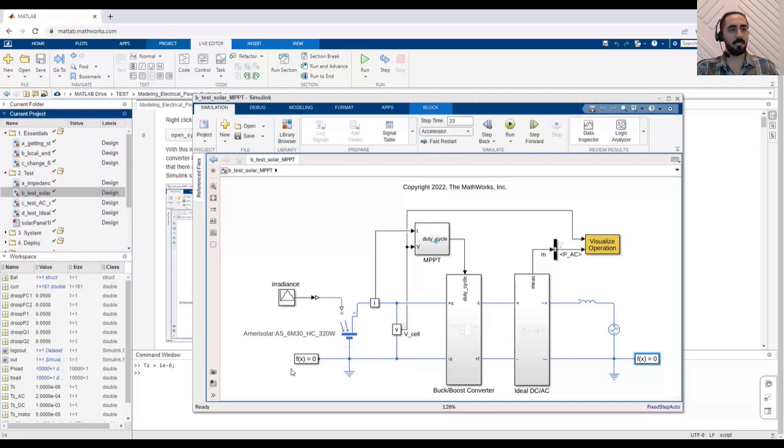Typically the AC step size is smaller, depending on your system, but you have the flexibility to change it based on your demands and requirements. In here, you can see TS_AC is 2e-4, and TS_DC is 1e-3. So two separate sample times for each network. And this brings efficiency to our Simulink model, optimizing based on the different characteristics that our networks have.